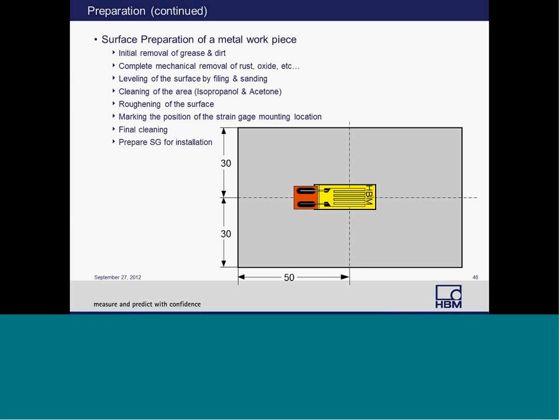We need to mark the position of the strain gauge. Again, finally, clean the area one more time to make sure that it's very clean, and then prepare our strain gauge for installation.